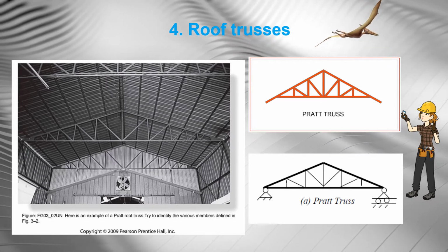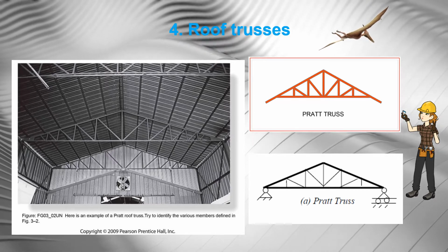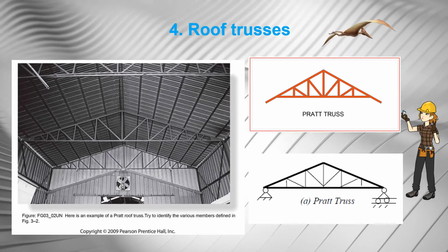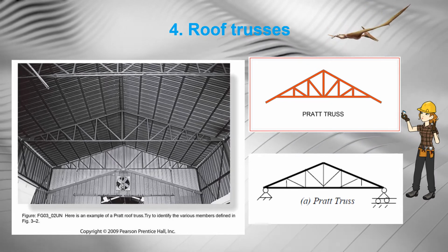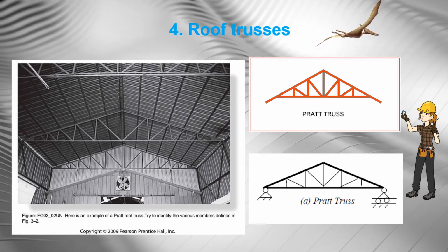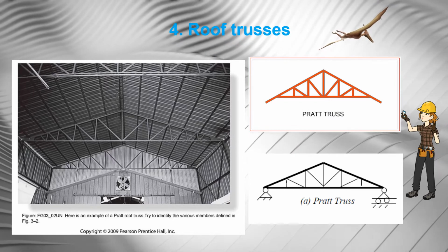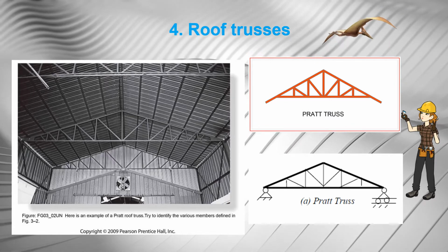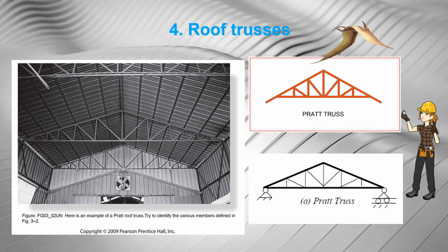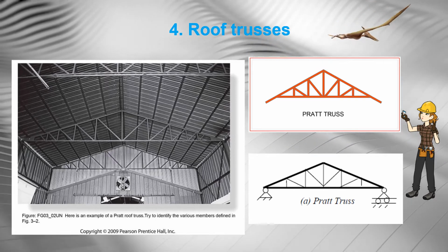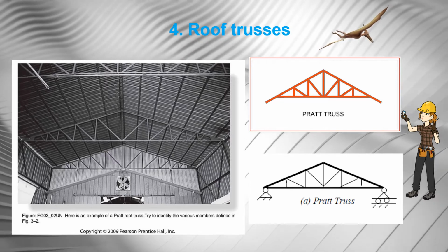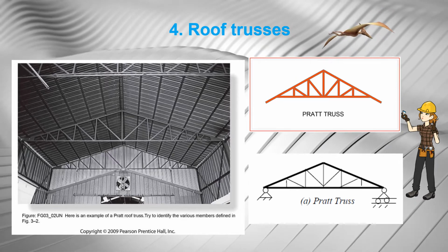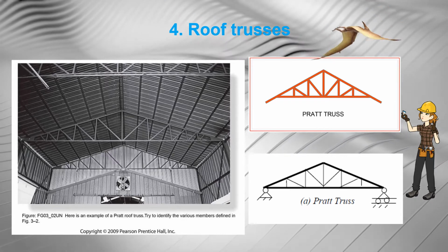Due to this, even though the overall bending effect is larger at midspan, the chord member and web member stresses are smaller closer to the midspan and larger closer to the supports. The typical span to maximum depth ratio of pitch roof trusses is in the range of 4 to 8, the larger ratio being economical in longer spans.